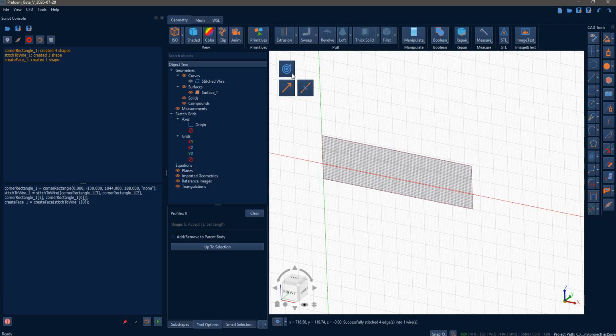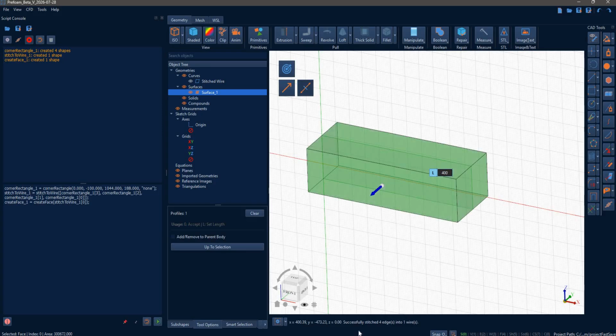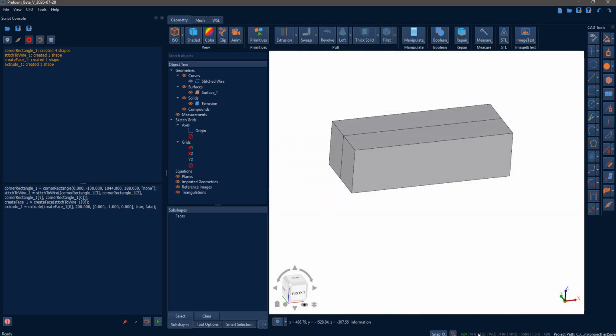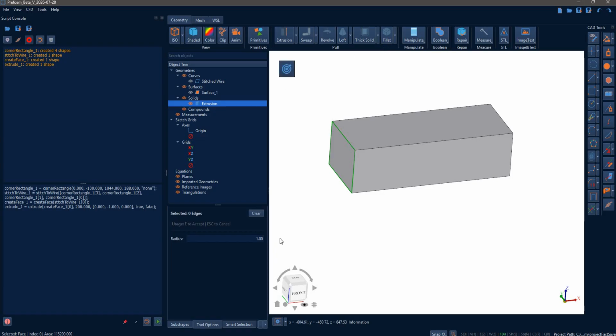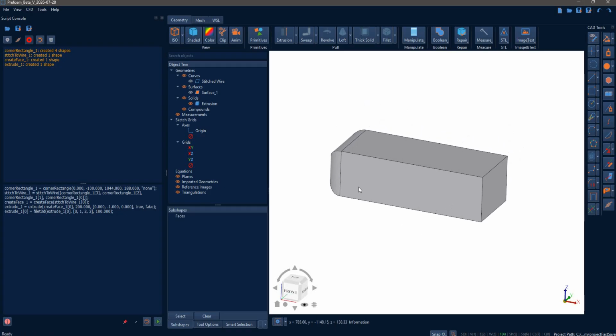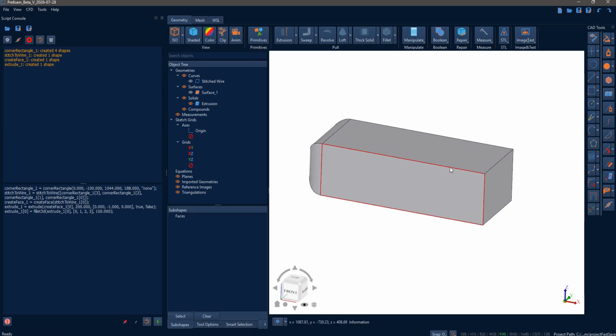Sorry, you need to select the whole face. Use the extruder in both directions, like 400. And then let us create a fillet right here. So I go under fillet, pass the face, and all the attached edges will be forwarded. And then hereafter, now the armored body has different kinds of slant angles over here. So this is very handy.